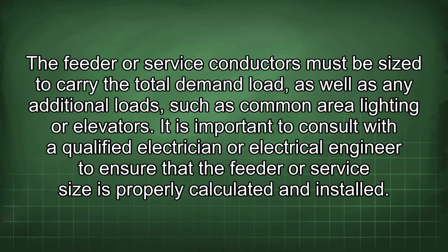The feeder or service conductors must be sized to carry the total demand load, as well as any additional loads, such as common area lighting or elevators. It is important to consult with a qualified electrician or electrical engineer to ensure that the feeder or service size is properly calculated and installed.